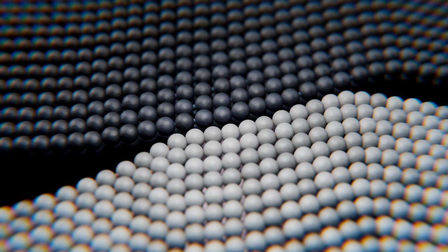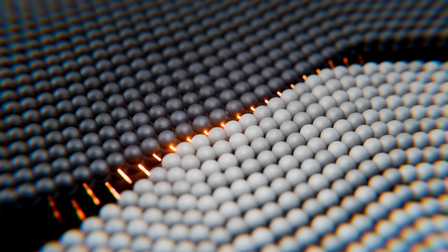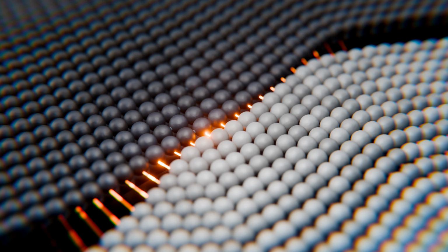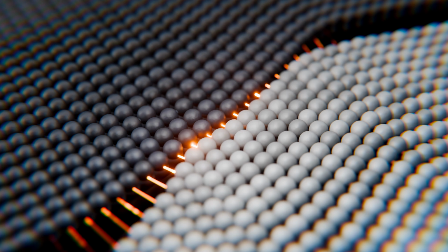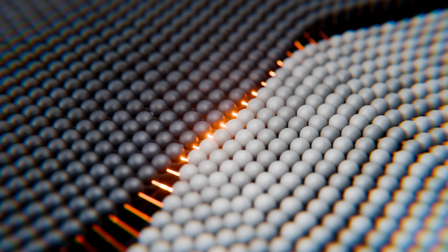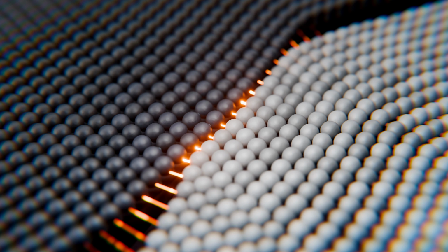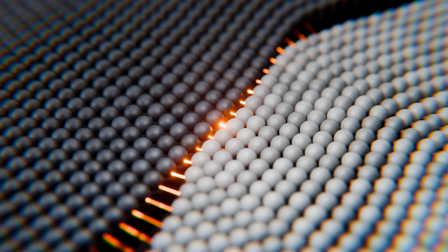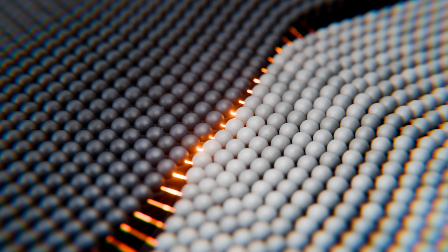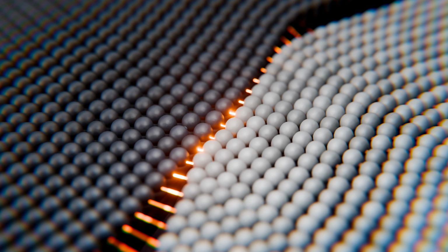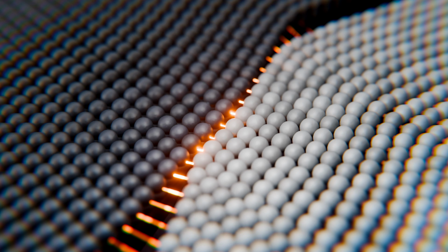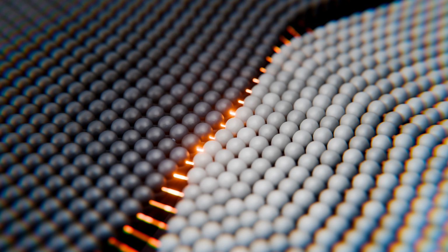As well as the mechanical interaction of asperities, intermolecular forces come into play in regions where the asperities are in close proximity. Atoms from one surface form temporary bonds with atoms from the other, and these bonds need to be broken for sliding to happen. For very smooth surfaces, these intermolecular forces can be a big contributor to the total friction force. It's also these bonds that cause kinetic friction to be lower than static friction. When the contacting surfaces are at rest, there's time for more and stronger bonds to form between the surfaces, making it harder to start sliding than to keep sliding.